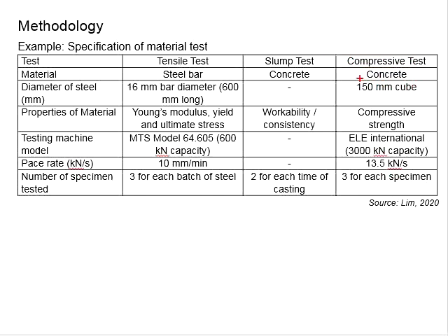You have to provide details of the concrete samples, from which you can determine the compressive strength: 150 mm cubes or 150 mm diameter cylinders. You know that there are also other sizes of cubes and cylinders. You need to check the standard carefully in terms of the recommended size of the sample.